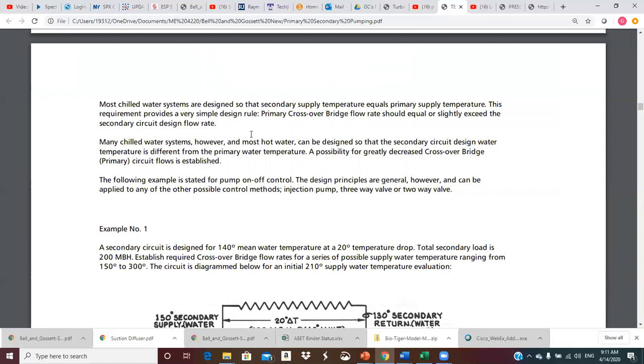In chilled water systems, we typically generate water somewhere between 40 Fahrenheit and maybe 44 Fahrenheit at the chillers, and then distribute that out in a large system like Tennessee Tech. We've got underground chilled water piping, and that water from the chiller plant is piped all around campus.